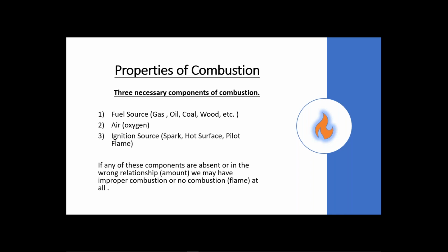And then the third one is an ignition source. That ignition source can be spark, hot surface, or pilot flame. Today, it's more popular in modern heating equipment to use spark as the ignition source. Years back, we used hot surface, and even earlier than that, we used a pilot flame.